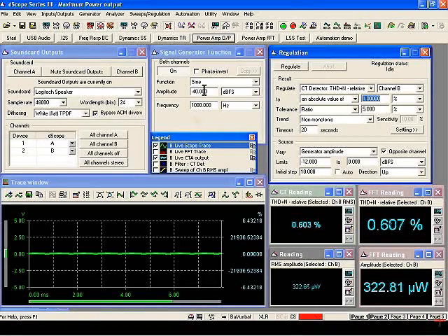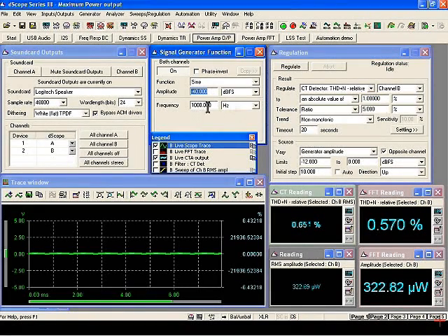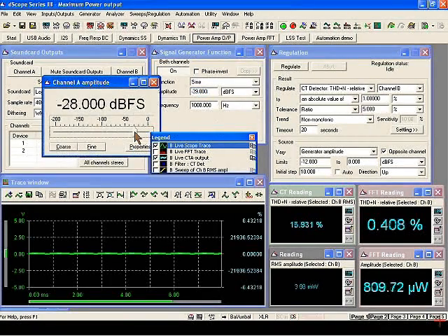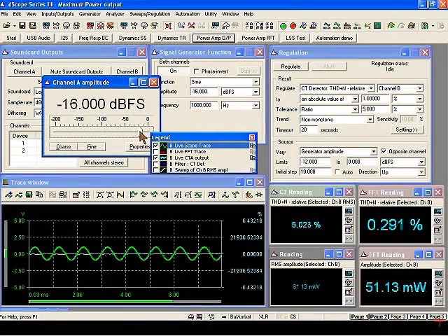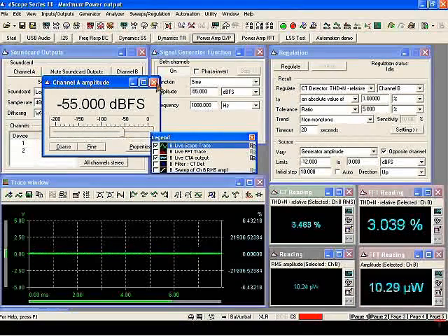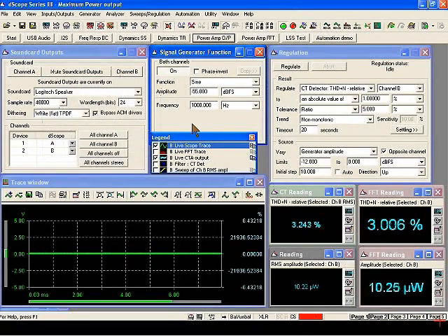Now, as I was saying, you could simply manually adjust the signal generator amplitude. You could even use a slider here to help you. But that would be a relatively slow process. It's an iterative one that requires a fair amount of manual input to keep an eye on the distortion measurement here and to determine exactly when you've reached the onset of clipping.